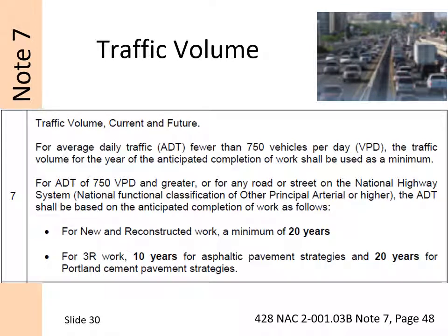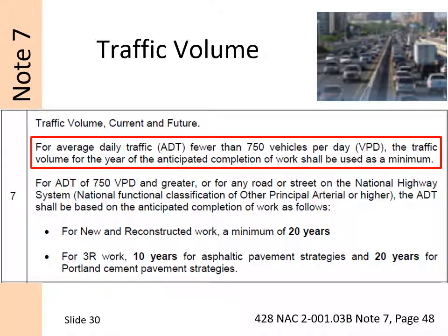Be sure to check Note 7, which is on page 48. It says that for lower volume roads, those with fewer than 750 vehicles per day, the note allows the use of the ADT for the year of anticipated completion of the work or project. It is not required to project the traffic volume ADT out to the design year for these roads and streets.